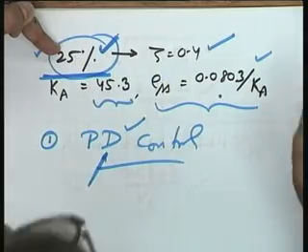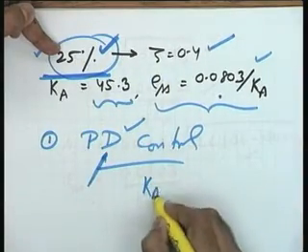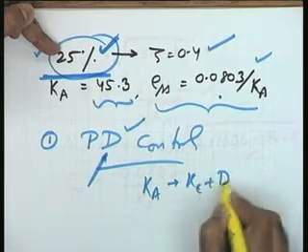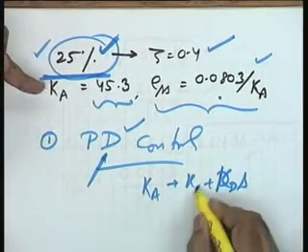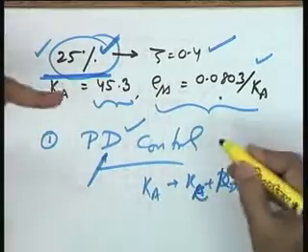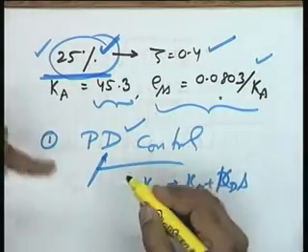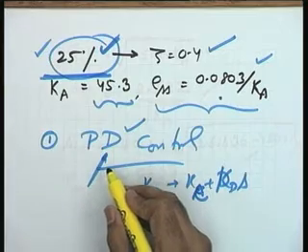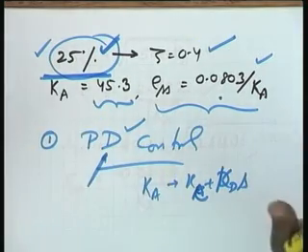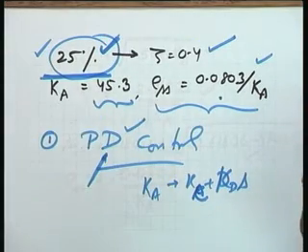A simple exercise for you. You replace your Ka by Kc plus Kd by S and satisfy yourself that it will allow you to increase the value of Kc, the proportional term, because additional damping is being provided by the derivative term. So, a PD controller can also improve the steady state error, please see.